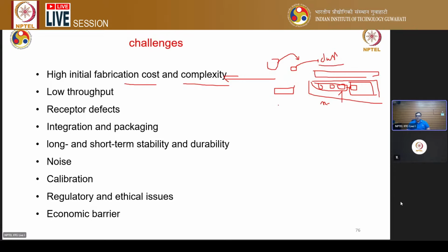Then the material that is basically your receptor. Say if you talk about a simple chemical sensor, fabricating the same receptor every time will be a challenge. There is a great variation if your process differs slightly. Also, the quality of the receptor changes heavily. So the defects in the receptor are very challenging to control when you talk at the micro and nano level.